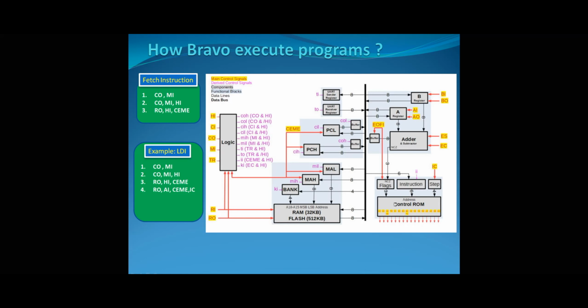If we didn't want to combine some of those signals, we would need more control signals coming out of our control ROM. Essentially, if we had dedicated signals for each operation, we would end up with probably 18 or 20 different signals, and just because of those 4 or 5 more signals, we would probably need to add a lot of circuitry to our control logic.